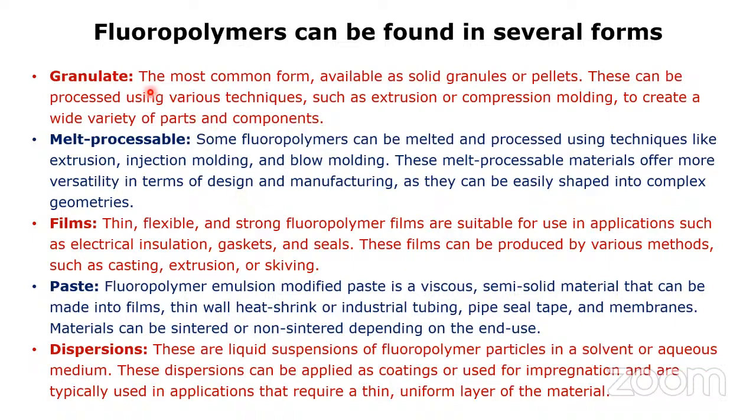First of all are granulates, or you can say beads, granules. In the very first lecture, I think someone mentioned pearls. Those granulates are nothing but pearls. The most common form is available as solid granules or pellets. These can be processed using various techniques such as extrusion or compression molding to create a wide variety of parts and components.